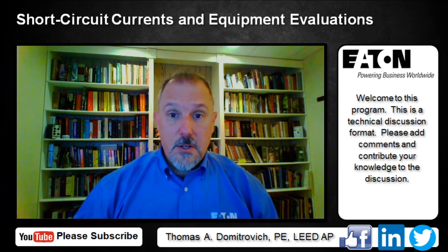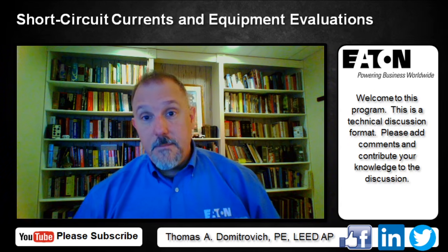The only time I'm doing a comparison on short circuit is when I'm worried about short circuit current ratings, or I'm worried about interrupting ratings, or I'm worried about selective coordination. And if I'm using my fuse, 200,000 amp short circuit current rating, can't get anything higher than that. So I'm not worried about short circuit current rating. Interrupting ratings, can't get anything higher than that. So I'm not worried about interrupting ratings. Selective coordination, 2-to-1 ratio, I don't know. Arc flash, maybe? I would say arc flash, you need to do that analysis.